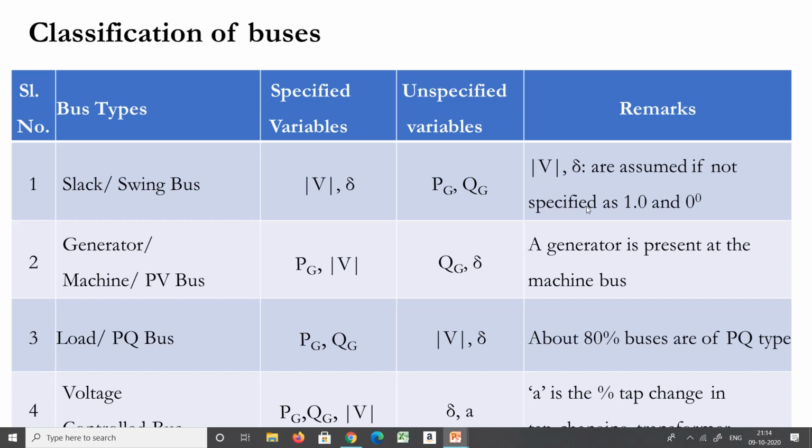And load bus means when real and reactive power are specified. The load flow quantities can be solved to find magnitude and phase of the voltage, and it is allowed to vary within a limit, for example plus or minus 5%.